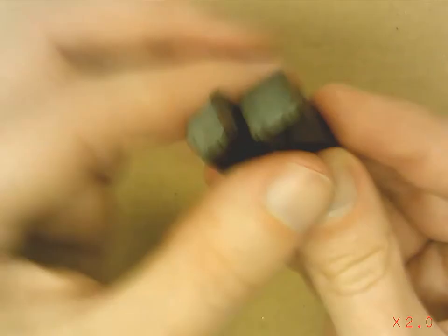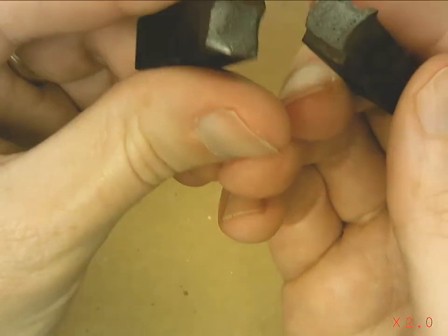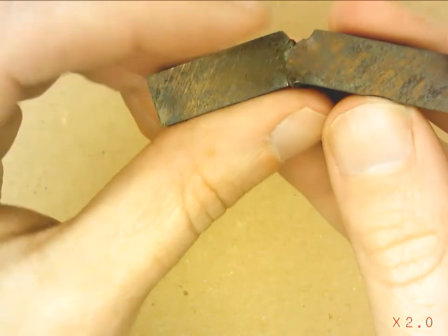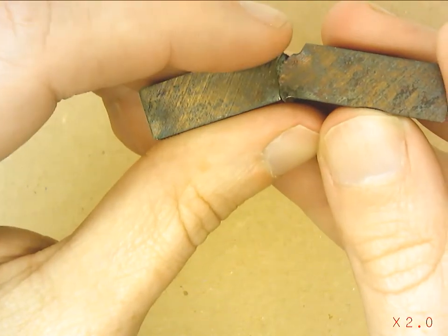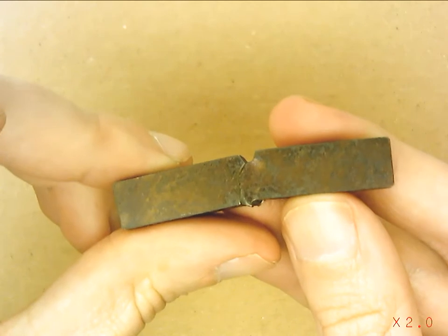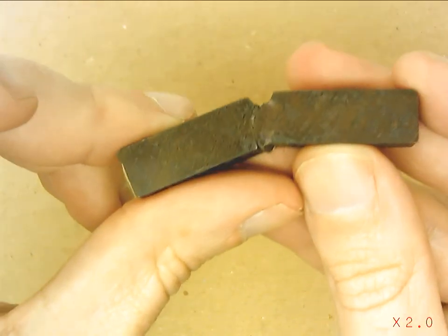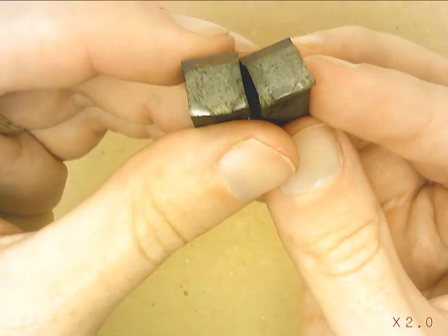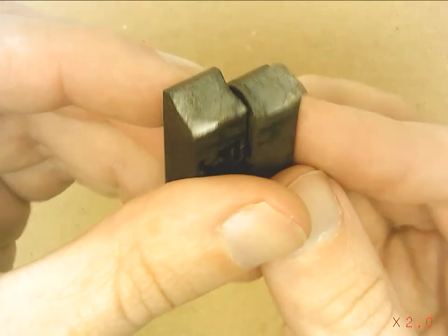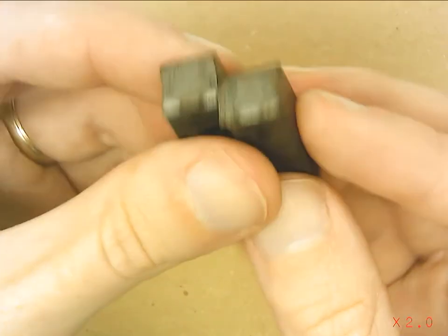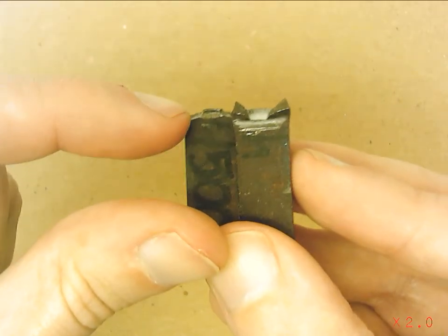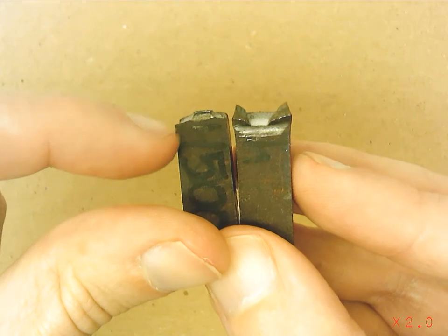Here's another ductile material. Let's see, let's play fit the pieces together. There we go. Our notch was up here. So the specimen was like this, impacted from the back, bent forward, snapped apart. These are ductile failure surfaces. They happen at a slight angle here.